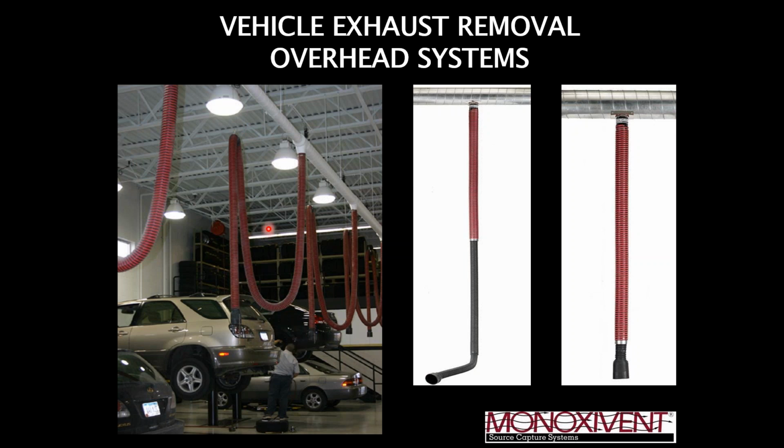When they stop pulling, that balancer locks or latches in place. You use it. When you're done, you pull it down again, and it unlatches and brings everything up and off the floor. So it works very similar to a hose reel, yet it's not as expensive as a hose reel, so that's a positive. The negative may be that because you have the loops of hose here, it's not as aesthetically pleasing. So it really depends on your customer, what their budgets allow for and what their tastes allow for.